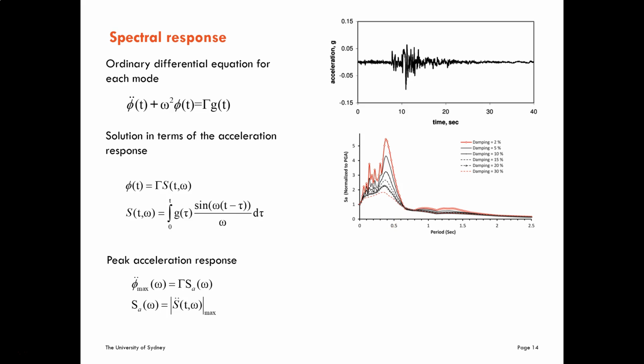And if the periods are small, the acceleration response is going to be small, but it increases almost linearly. This solution is with no damping, but I can extend the solution for different damping ratios, and the response is going to decrease if the damping increases. So I can calculate this spectral response against period given any acceleration versus time. This is going to be very useful.